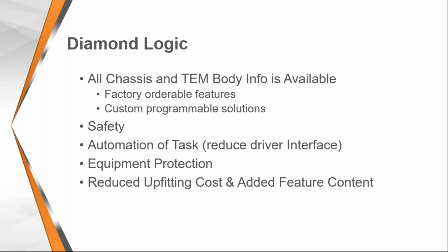Automation of tasks, several of the feature codes, and I'll give you an example of an air suspension dump. The driver's parked, he flips the air suspension dump, and the rear of the chassis drops down, if it's a box type truck and he's offloading something. If he forgets to flip the switch back to its normal position, as soon as he releases the park brake and takes off, the automated task at a certain mile an hour will automatically raise that air suspension back up.